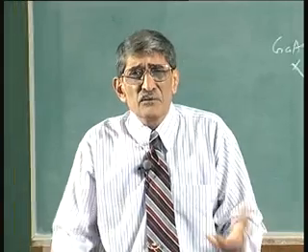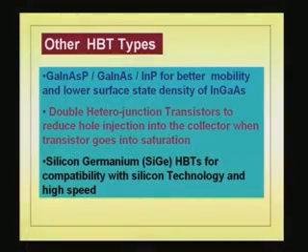Okay. Now, why should you go for this? This type of structure has benefit. One is gallium indium arsenide, as you know, has much better mobility than gallium arsenide, okay? Because indium arsenide has got higher mobility. When you mix with gallium, gallium indium arsenide has got better mobility, but in between indium arsenide and gallium arsenide. The band gap also is different from that, lower than that of gallium arsenide. Okay. Now, but you get fairly decent band gap there, but main reason is it gives better mobility. So, on the top of that, of course, you put this material which has got a wider band gap region.